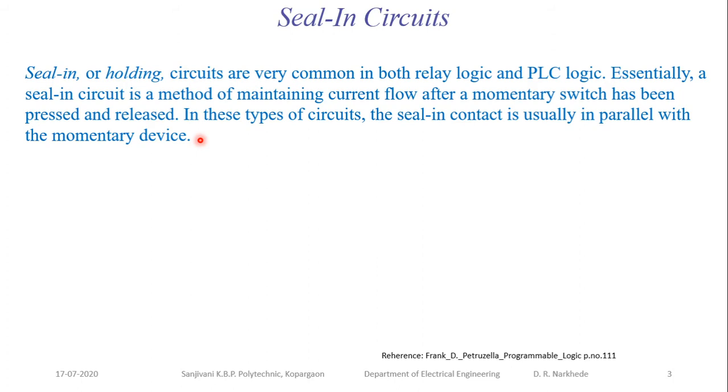The second switch, which you use for a doorbell, is the press and release type switch. In that switch, as long as pressure is applied, it will remain in the energized state. Once the pressure is released, once you remove your finger from the switch, it will disconnect the circuit. So this is the press and release type switch. Now, for industrial control, we will prefer the press and release type switches. Those are called momentary press switches.